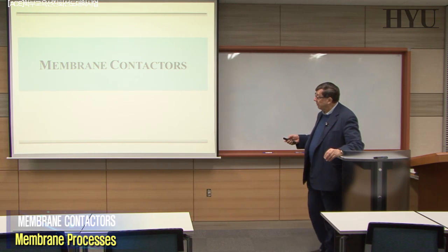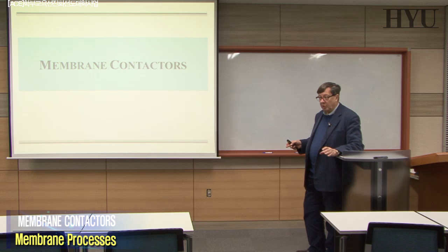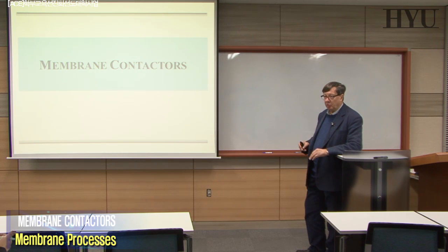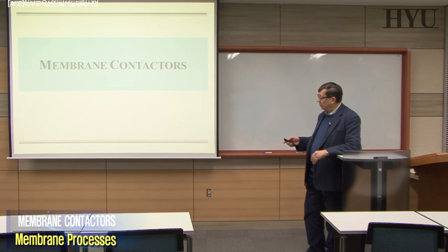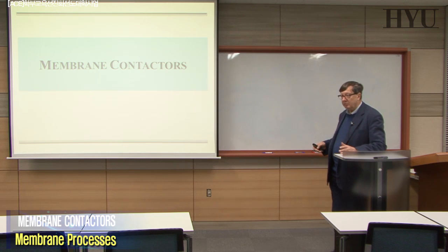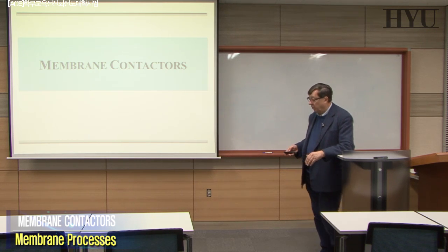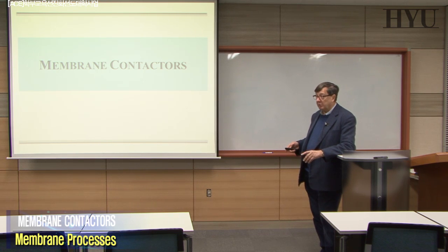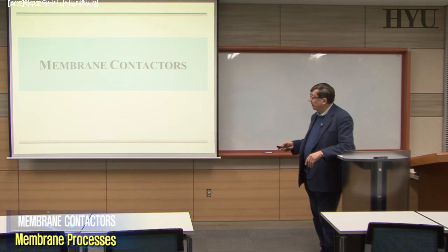When you are discussing membrane contactors, we are not looking anymore for membranes with the property of selectivity. The function of this system is just to optimize contact, hence the name contactors, between different phases: liquid, solid, liquid, liquid, gas, liquid, etc.